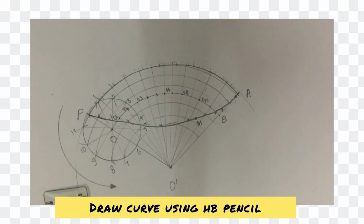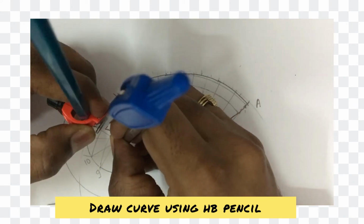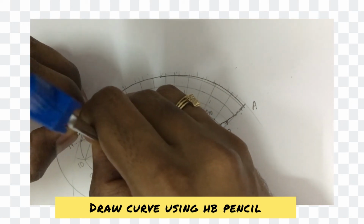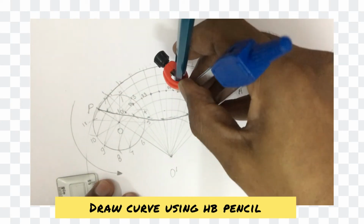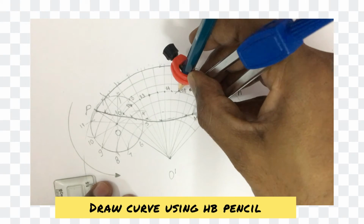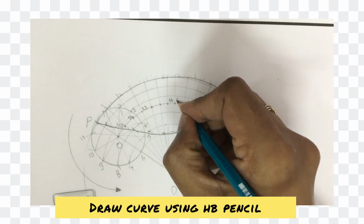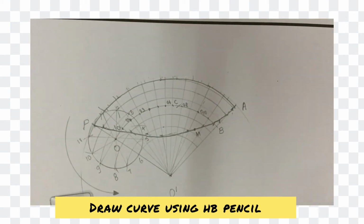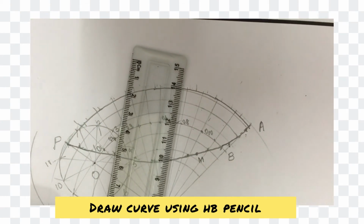Now with M as a point, the same construction which we have done for the epicycloid, and with M as a center, cut the locus of center, isn't it? This is the locus of center, OB. Let that be point C. And what we are supposed to do? We are supposed to join this C to the center.